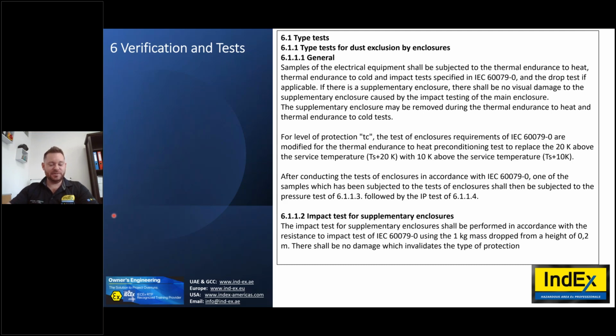Now, EXT, the consideration you need to make is, is there potential for dust to travel up the conduit? Is there potential for pressure piling to happen? If you have 100 lights in a row with the same common conduit system, no, there is no need for conduit sealing. As long as IP5X or 6X is maintained throughout, that is sufficient.